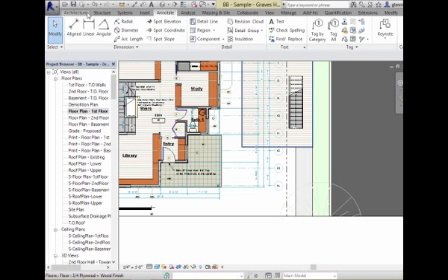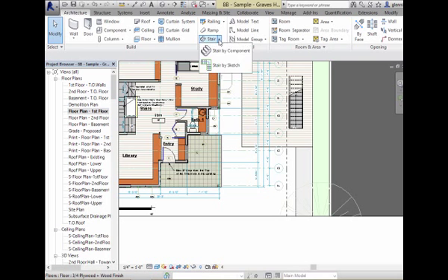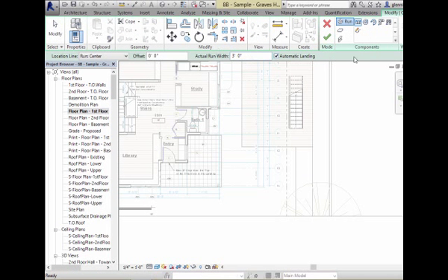Some of those variations, and we started on some of them last time, are back in the good old stair tool. In the stair tool, you will find we're doing runs, sections of straight runs. A very popular one is to go up about halfway. So I've created 8, 6 remaining. We come back to 7. It doesn't have to be even, but conventionally it often is. I'll place half the stair right there. Then I'd like to keep going with the stair.